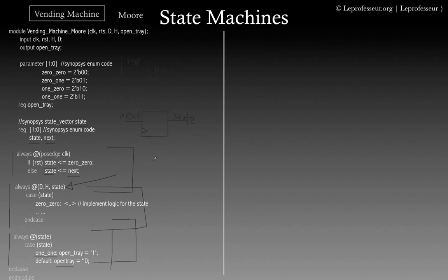That way you will make sure that you design synthesizable digital circuits. If you want to simulate, and if the simulation tool needs some special delay, you can specify that using delay directives in Verilog just for simulation purposes, before any assignment if you have to, but for synthesis it doesn't make any difference.